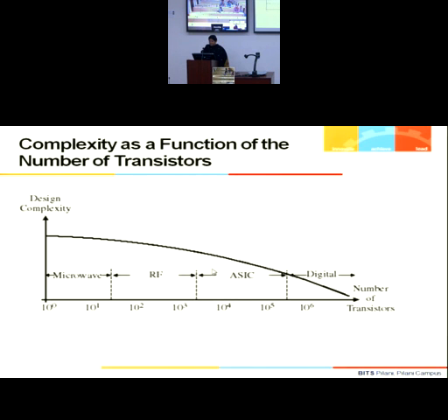Can you say for the ASIC, the design complexity is from 1K till approximately 1 million transistors? Okay. So 1000 to 1 million transistors. Normally ASICs are developed in this range, and only for digital applications it is even higher, because digital is something that IC technology has adapted itself to. The initial thrust was on digital design, so the technology that was developed was developed for digital design.